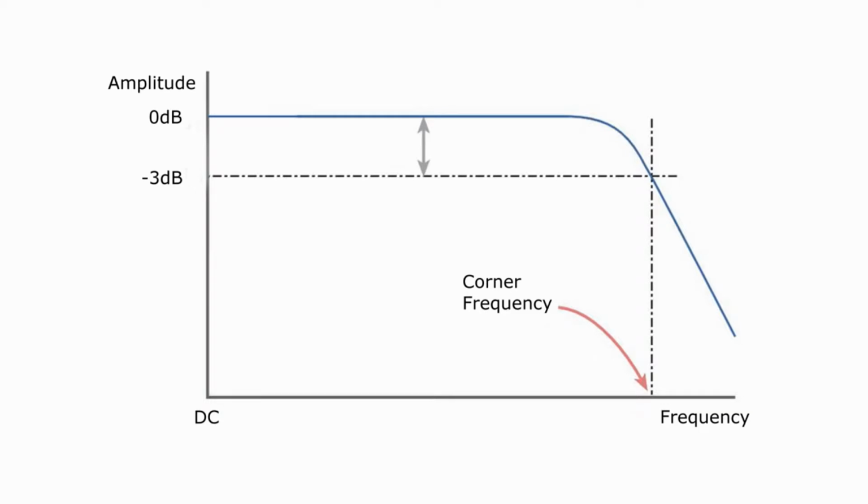The end of the attenuation band is the point at which the electrical output becomes immeasurable by the ADC. This point is also the start of the rejection band, which stretches out to infinite frequency. There are two limitations to analog to digital converters. The first is the sampling rate, and the second is the smallest resolvable voltage. Both of these limitations play a factor in defining the optimal setting of the low-pass filter's corner frequency.